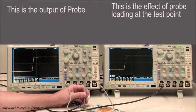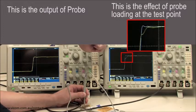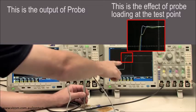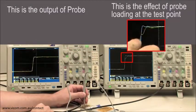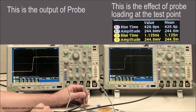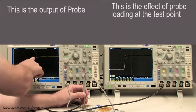Here is an example of a passive probe from Agilent that has 10 pF input capacitance. Again, you can see how the probe's input capacitance is affecting the signal you're trying to measure. The front corner of the signal contains all of the high-frequency signal content, but that information is being compromised by the probe. You can see how the front edge is rolled off. Once again, how does the probe harm the signal? The rise time has been degraded to 1.1 or 1.2 nanoseconds, and this is what is happening at the test point. The signal hasn't even started through the cable, the comp box, and to the oscilloscope.